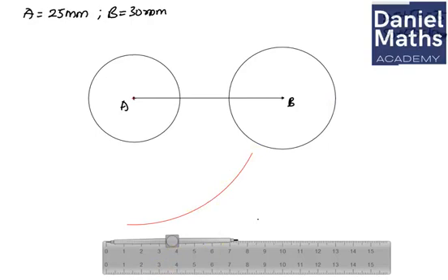So what I'm going to do now is to extend this up to 80. So you open up your compass to 80. This is 80. I have 80 at this point. Once you've gotten that point, move your compass to point B. Move your compass to point B, and then you bring up your distance. Bring your pencil. You can start from this point, and then we're going to cut again.